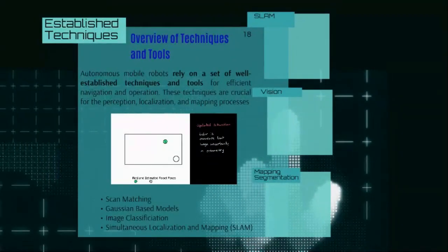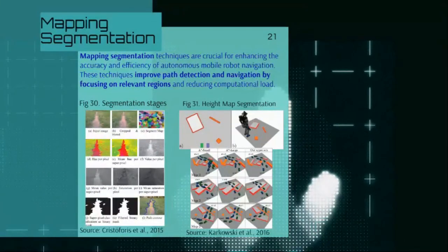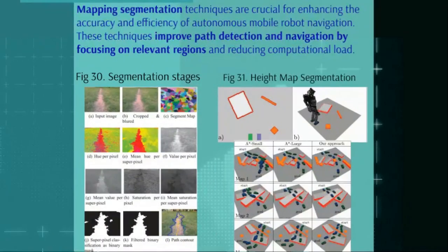These tools are very reliable and widely used in perception with vision systems. We also have segmentation techniques, which are very common in robotics. For example, if you segment a road environment, and you don't wish your robot to calculate a path over the grass, the grass is filtered out with Gaussian filters.